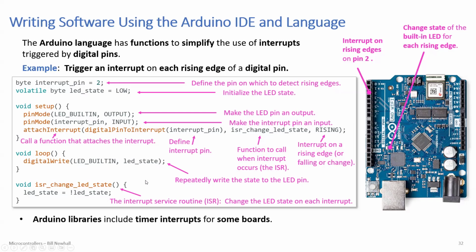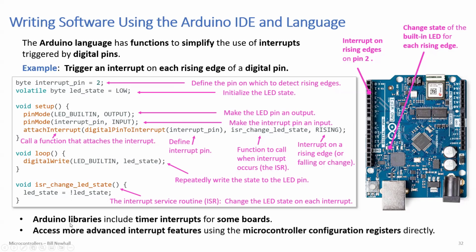Okay, so this is triggering an interrupt based on hardware input. You can also, on some Arduino boards, interrupt on timers. Okay. But again, this is the Arduino language. You can actually access more advanced interrupt features using the microcontroller configuration registers directly.